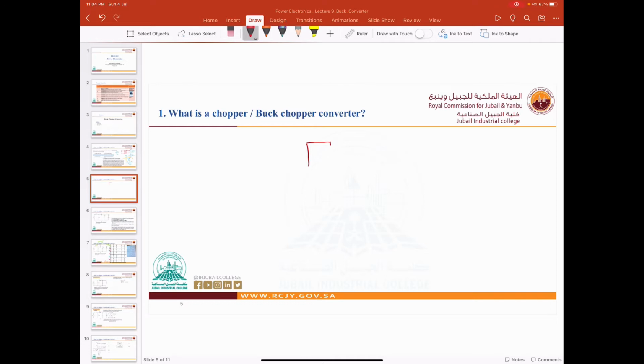This is our converter, right? DC into DC. This is our input. This is our output here. So this is Vin. This is V out. Plus minus here, here plus minus. So we are converting DC to DC. Now, if we use PWM, pulse width modulation, right? If we use a chopper, then the input signal will be like this. Now this is the input signal, the same signal. Now the output will be like this. So we are taking part by part, right?